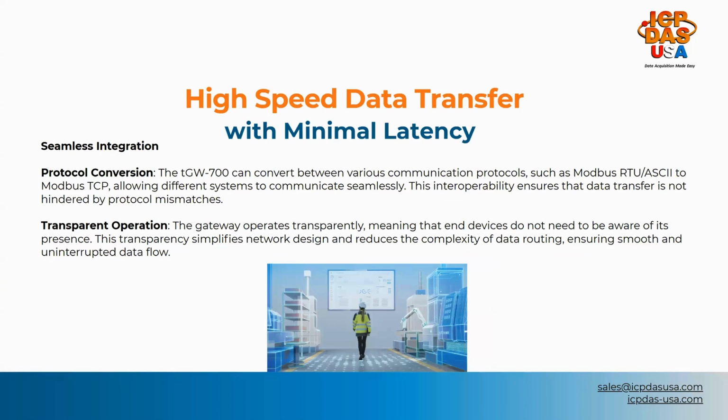Protocol conversion. The TGW-700 is capable of translating between different communication formats like Modbus RTU or ASCII and Modbus TCP, so that devices using different protocols can communicate without issues. This makes it easier to integrate newer Ethernet-based systems with older serial devices. Transparent operation. The gateway works behind the scenes, so connected devices don't need to know it's there. This transparent behavior helps simplify your network setup and keeps data flowing smoothly without requiring extra configuration on the end devices.